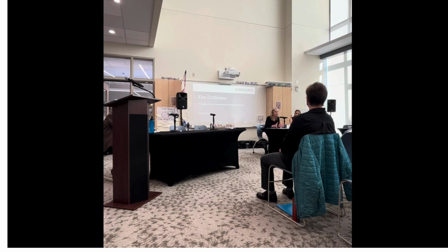So what is the support about? For Mass Save support, we were able to come in, as I mentioned earlier, and help set that energy budget. When we started with some of these early projects, we didn't have a clear number in mind. Shin reminded me of this earlier. We didn't have a clear energy budget target. Now we know what that budget is for schools, and I can tell you right here today, it's a 25 energy use intensity, 25 EUI is the target for schools. We strive for that. We promote that with all the school projects. Even if you can't work with us, even if you're with a city or town that is ineligible, I strongly encourage you to set an energy budget.